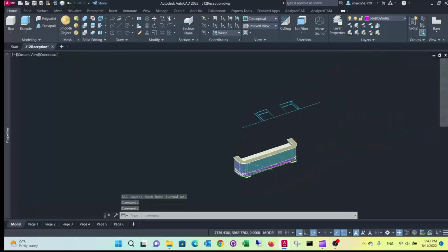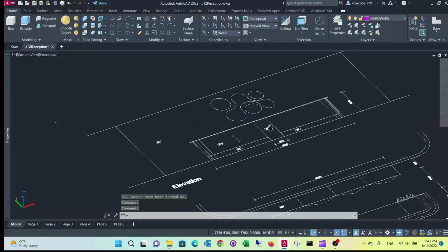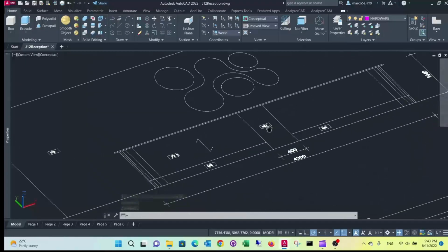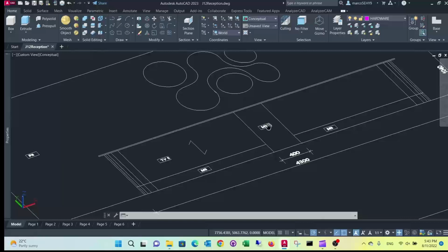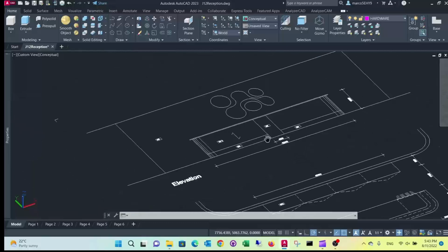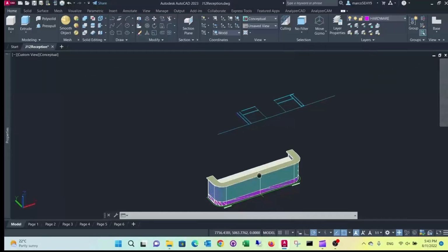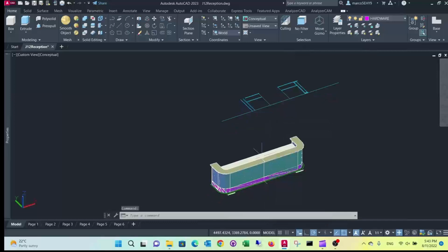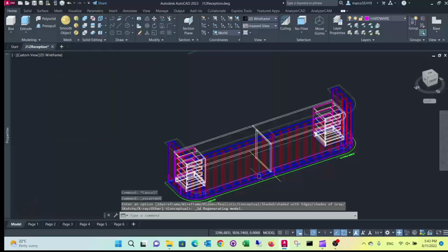The architectural drawing also shows us a metal front panel going up through the center of the counter. I think we should use a 16 mm board for this and cover it with stainless steel. We can now draw it by creating the substrate first.